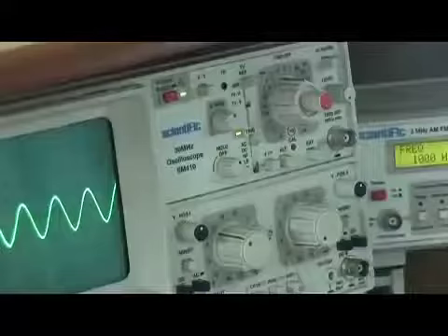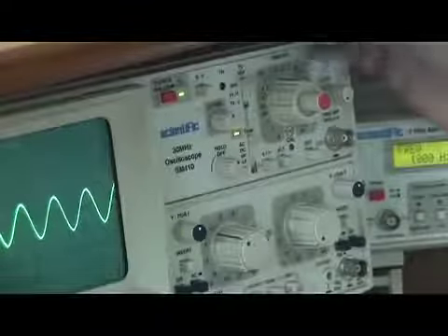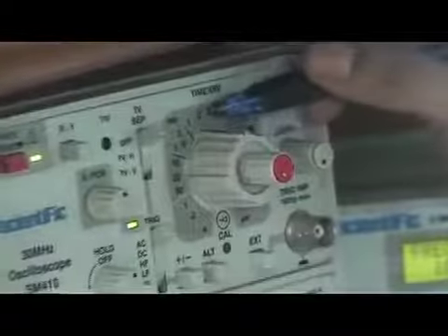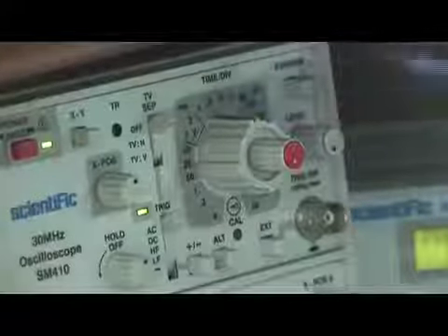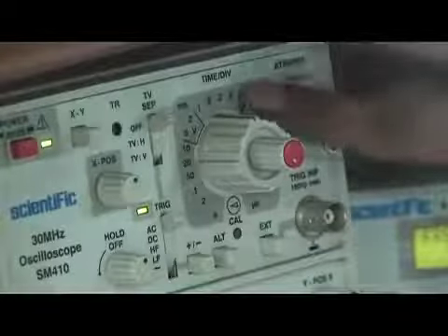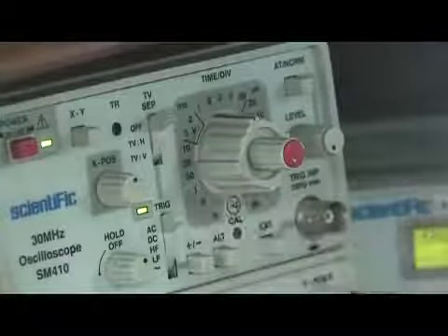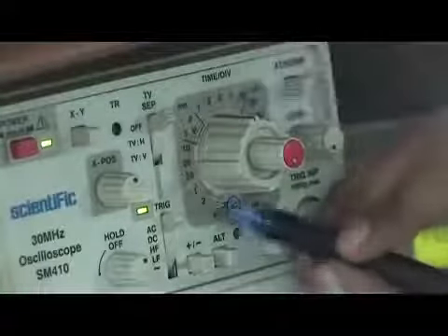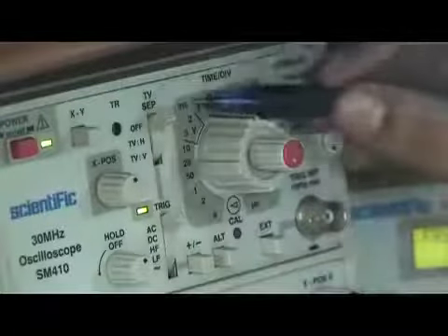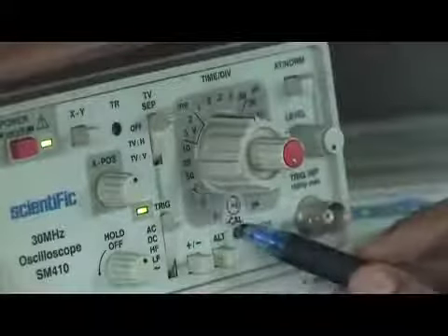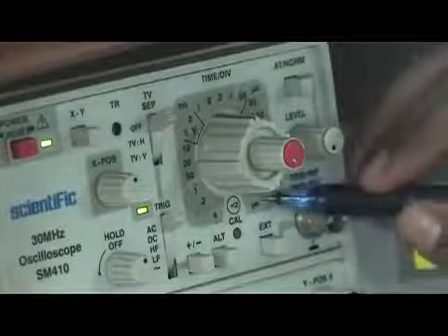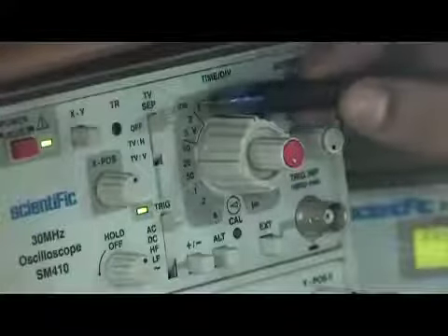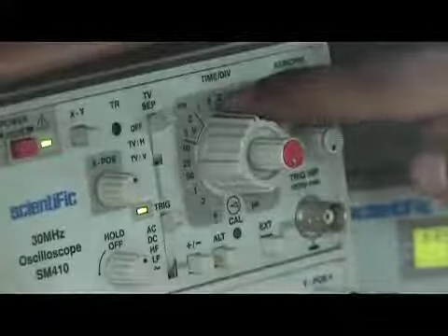So it is 2 into, where you can see this knob lies, there is a line here, this lies at 0.5. So 2 into 0.5 is how much? 2 into 0.5 is 1. What will be the unit? From this gap till this small gap, between these the unit will be milliseconds. From this gap to here, the unit will be seconds. From this gap till here, the unit will be microseconds. Right now we are in the range of milliseconds. That's why it is 2 into 0.5 milliseconds.